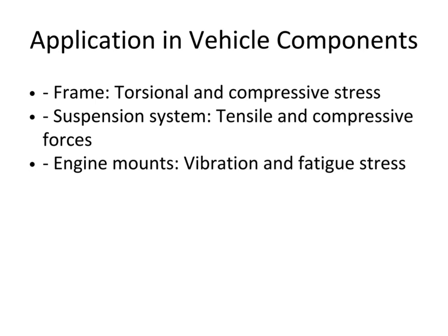The last one is the engine mounts. In engine mounts, we apply vibration and fatigue stress. When a car engine is running, it vibrates violently, so we put it through vibration stress so that we can see how much vibration it can stand. And the last one is fatigue stress. We put it through a lot of work to see how long engine mounts can work until they break or get fractured permanently.